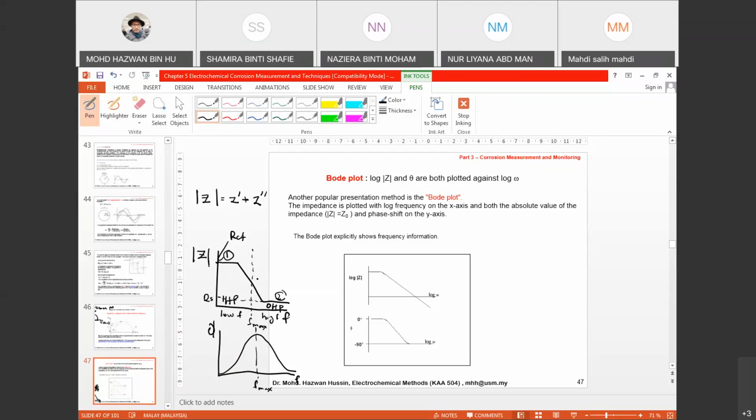If you have one slope, or one peak, this tells you that you have one capacitor. So at the end, you put in your mind: I have two flat lines, so I have two resistors and one capacitor. The capacitor will be the capacitor CDL.